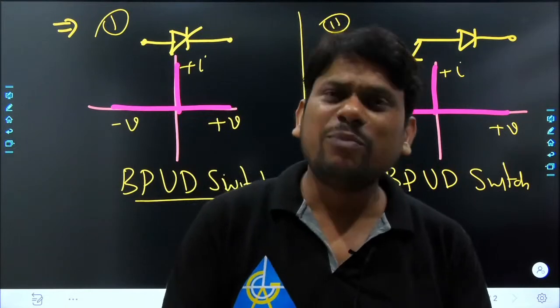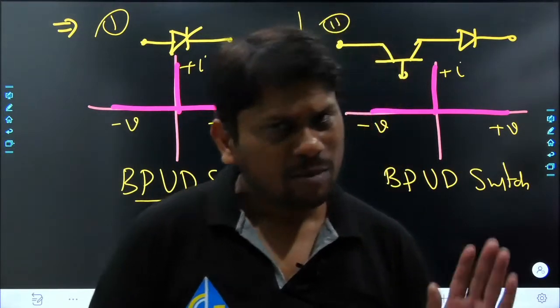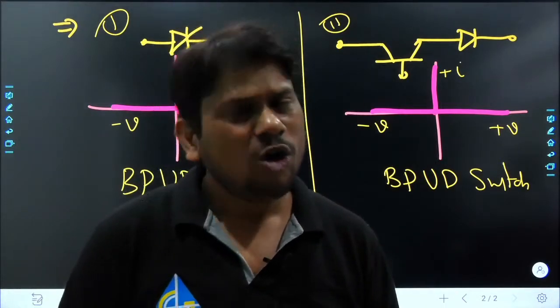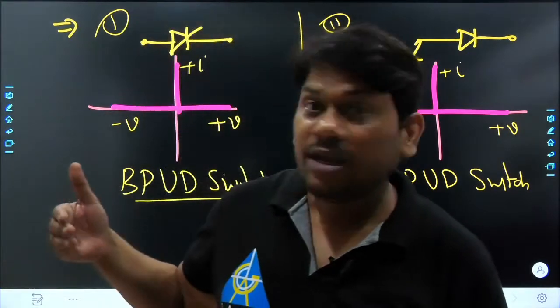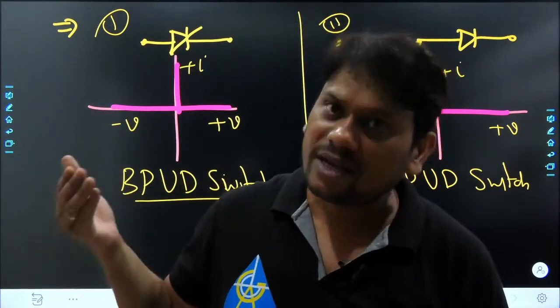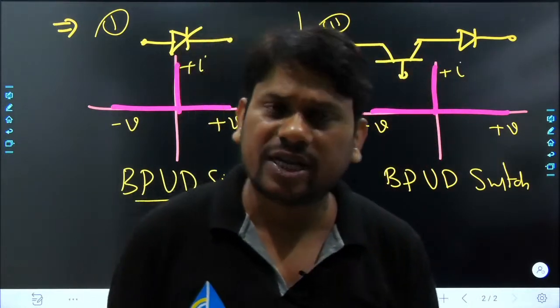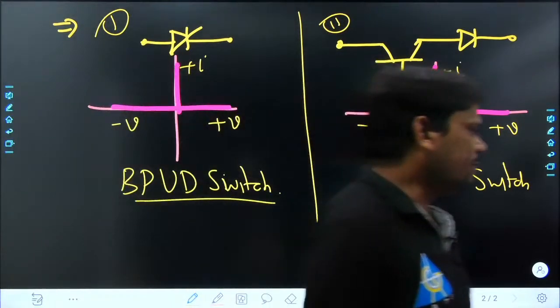But just keep one point in your mind. For low and moderate power ratings, BJT, IGBT and MOSFET are somewhat popular. Obviously, not BJT alone; IGBT and MOSFET are somewhat popular. And in high power ratings, SCR is popular. That is the point. So due to all those reasons, we want to design a switch module. Now tell me, is each and everything clear? Please everyone, tell me fast.